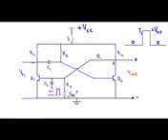With the VBB connected, you'll see that the negative terminal of this VBB is connected with the P-type base, and the positive terminal of this VBB is connected with the N-type emitter. Therefore, initially the base to emitter junction of the transistor Q1 will be in reverse bias, as the base to emitter junction is not forward bias in case of this transistor Q1. Therefore the transistor Q1 will be in off state. Therefore I can disconnect the collector and emitter terminal of this transistor from our original circuit, as it is in off state or in cut off mode.